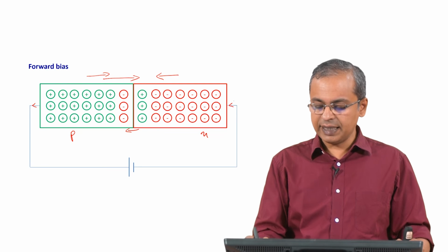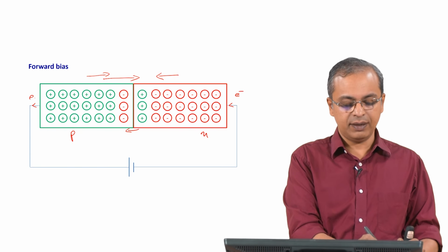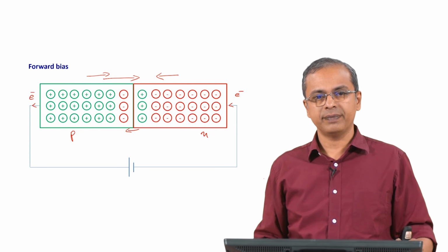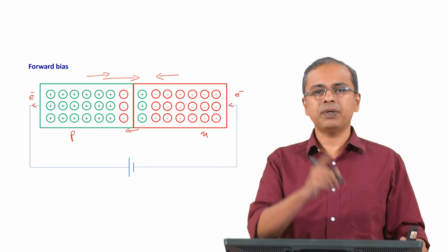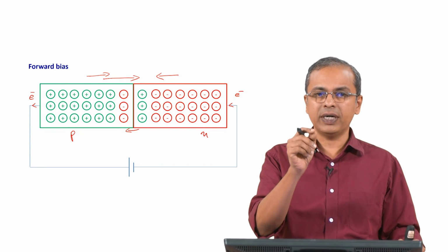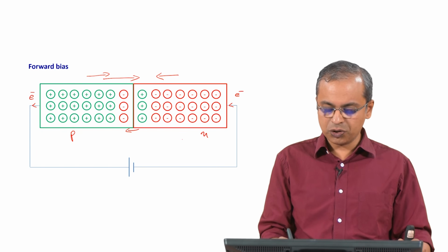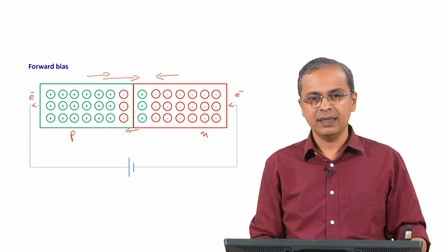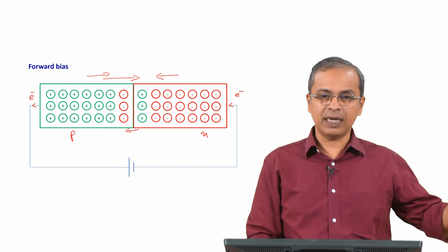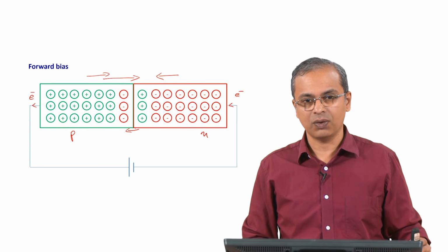So, an electron is entering from the right side and exiting out on the left side of our sample. You can think of it that way. If you remove an electron, it is the same as having added a hole there. You were short of one bonding electron, and one electron crossed over from the n side and occupied that site, and then you took that electron all the way to the left end and took it off the circuit, and therefore you have essentially reintroduced that hole.